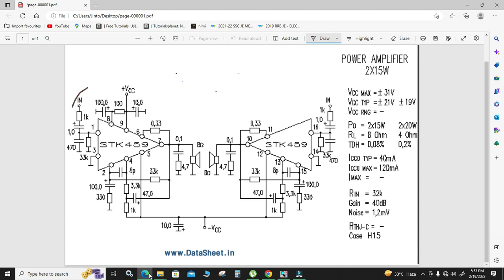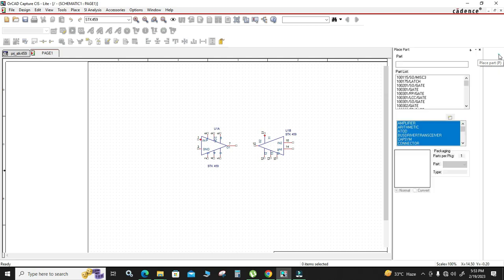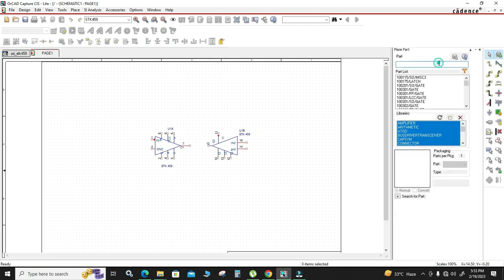First we start with this part, the first pin. It's near a resistor, so we use the shortcut P, place part. Then search for the resistor. You can see many types of resistors available here. I'm going to choose this resistor, a resistor discrete. It's a nice one, and it has a designator, and its value is shown there.